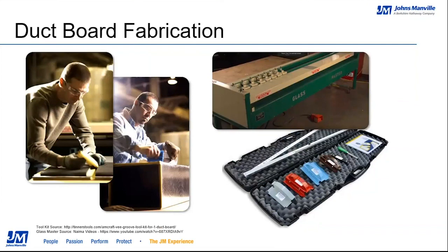The duct, after grooving, though, is stapled via the FSK staple flap with outward clenching staples that Brennan discussed for duct wrap, very similar setup there. And then you seal that with a UL 181 pressure-sensitive tape, and you squeegee it down as the person's doing there with that plastic squeegee to ensure a tight seal so there's no loss in energy.